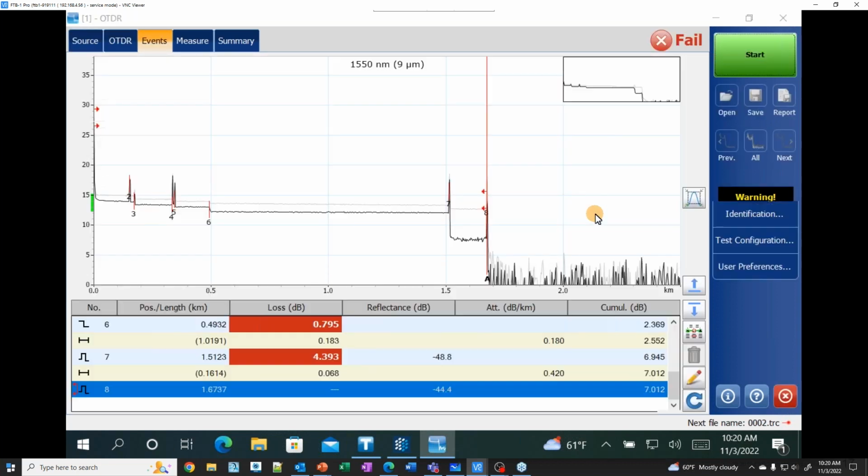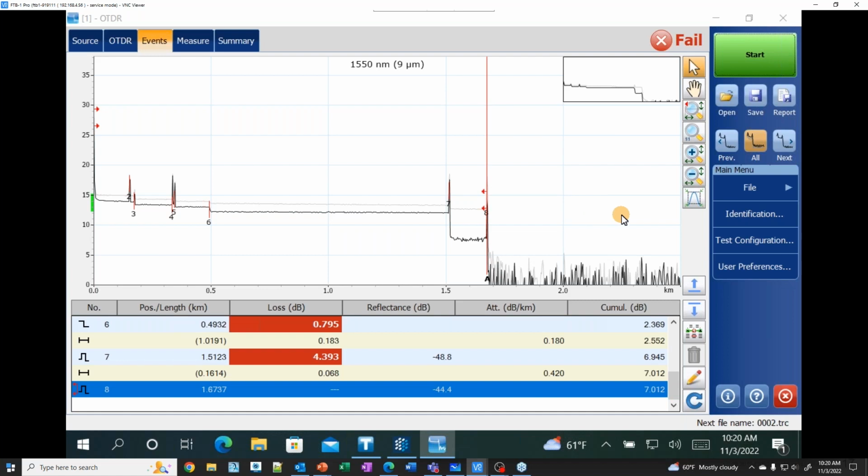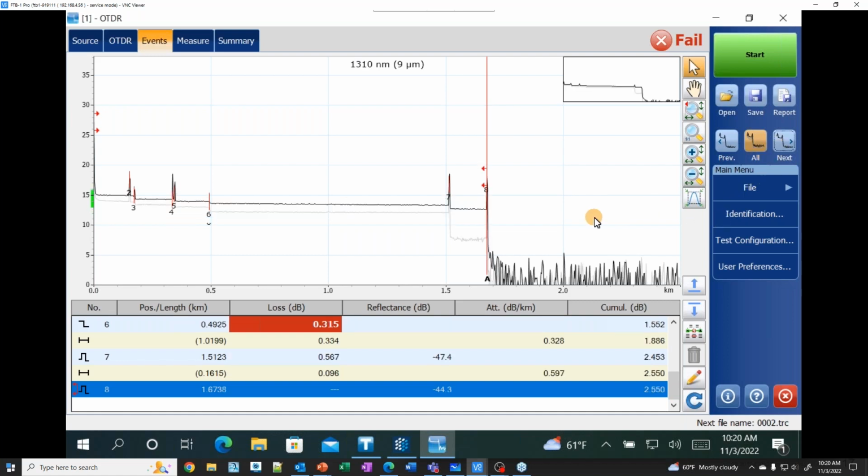So we're going to show what's happening here. Imagine the systems that you have today that are running 1310. Your short reach, 20 kilometer, 30 kilometer systems, single wavelength stuff, probably 1310. A lot of cell towers, backhaul, a lot of 1310. So as you increase your bandwidth going to 5G, going to 2, 6, 8 gig services to homes, all of a sudden the F2 side, the distribution side of it, needs more bandwidth, which part of that includes going to DWDM or increasing your spectral efficiency. That's getting you into the C-band, into the 1550 range.